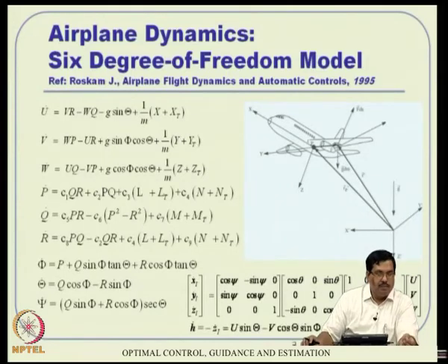Then it goes to the next level of what is called CFD, computational fluid dynamics, where they talk about generating it in a grid point sense, using finite element, finite volume, all sorts of things. So, this will give you a somewhat more accurate sense. Remember, the flow pattern over this aircraft body is not very much in tune with the assumptions we make in the first cut model. The first cut model is all clean configuration, the surface is fairly good and so on. So, going one level higher, CFD will account for all these protrusions, and all sorts of wing configuration, whether you have a fin out there, and try to give better accuracy.